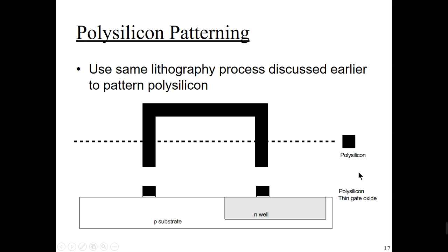And after that, polysilicon has to be placed where I want to design the gate terminal. The main intention is to place the polysilicon at the place where we want to make the gate terminal. In CMOS we have an NMOS transistor as well as a PMOS transistor. For both the NMOS and PMOS transistor we have one gate terminal. Each transistor uses one gate, that's why polysilicon is placed here for one transistor, and this is for one more transistor.